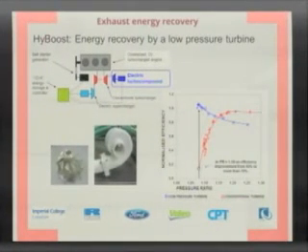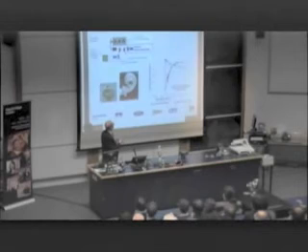Two more. This is an innovation that we want to tackle, the exhaust gas still remaining after the turbocharger. I've been telling you about turbochargers a little bit, the turbine. Then there's still gas and there's still energy before you exhaust to the ambient. So why don't I design a new turbine, which is capable of recovering that loss of energy. Again, normalizing, the efficiency is not 100%. That would have broken a few laws. But it's normalized, about 72% or so, I can tell you.